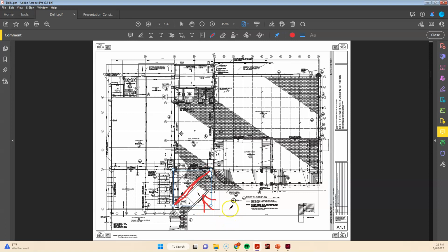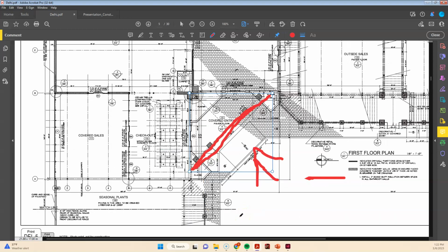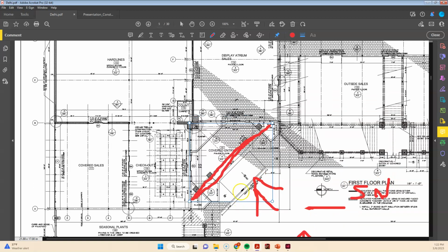And before I forget, let me get back to the north arrow, which is now here. So now the north arrow has rotated, right? It was facing north on the page, right? So north on the page is project north. This is solar north, okay? And I know that because this entry was facing southwest before, and the sheet, the building, has been rotated.